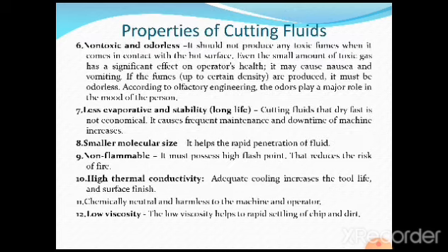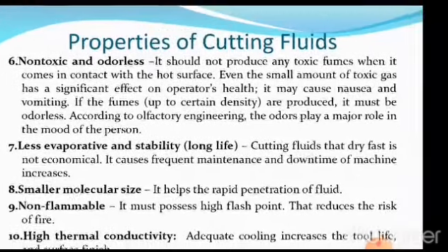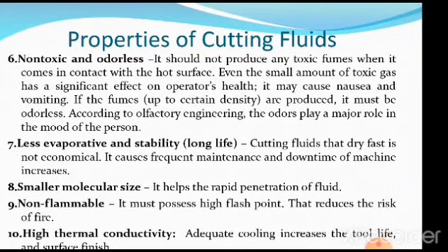The sixth property is it should be non-toxic and odorless. Yes, this is very, very important. It should not produce any toxic fumes because whenever we use the cutting fluid, its main function is to absorb the heat. So when it starts absorbing the heat, it should not give off fumes which are harmful to the operator. When it comes in contact with the hot surface, even a small amount of toxic gas has a significant effect on the operator's health.